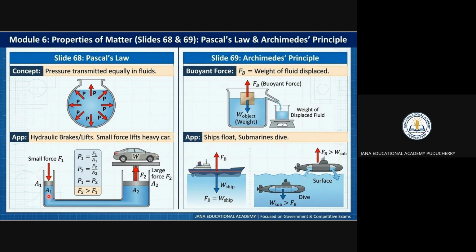What happened due to that? There is some fluid inside, and the pressure is transmitted. It is going to give more force on the larger area, so it is going to lift the car up, right? So what do you understand? By using a small force on a small area, the pressure will be more. That pressure acting on the higher area gives a higher force. That is P1 is nothing but F1 by A1.